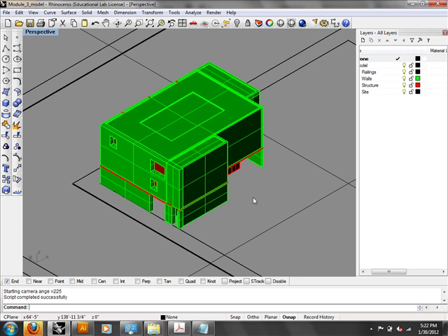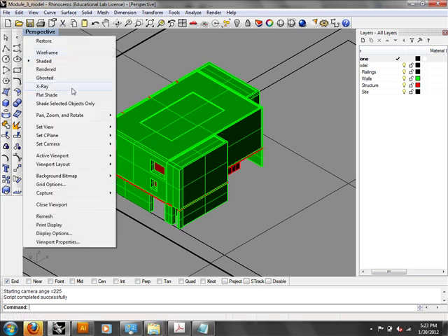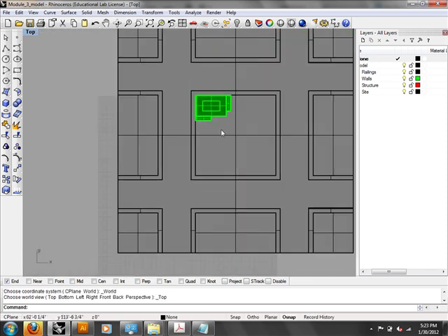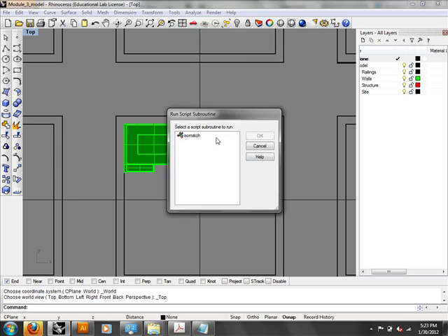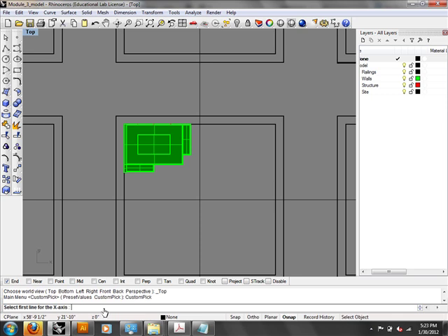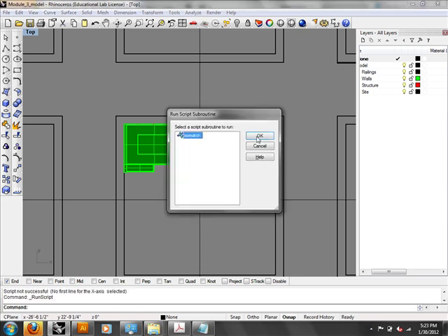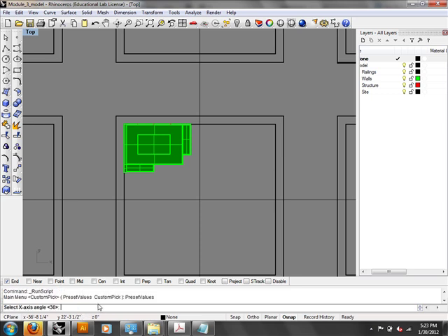So that looks pretty similar, but that's actually isometric. And again, with this one, it's all in the script, so you can rotate the view within the script, and you can type in whichever angle you want. It also doesn't destroy your model, it makes a perspective viewport. So if I run that again, I can just go up to Tools, Run, and then choose my script. You can also do custom pick, and that actually lets you draw the angle. The other thing I can do is change the values. I have a list of these values. For an isometric, it's 30-30. For a dimetric, you want to do 42 degrees and 7 degrees.